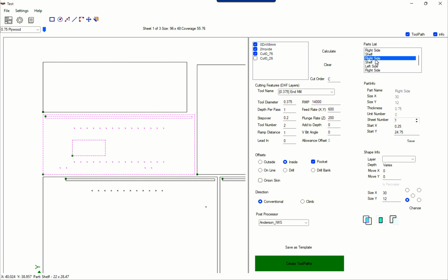If we clicked on the rectangle to draw and had the mouse up be off of the part, it now essentially becomes a part of its own and is not associated with this right side. And we click on that part and we see it is a perimeter cut, meaning that that is really a part of its own.